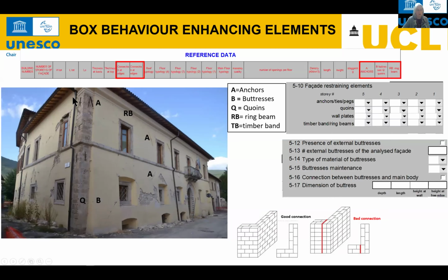So although this building looks very traditional and historic, indeed, this can be quite easily recognized as a later intervention, possibly in the mid to late 20th century, where a concrete ring beam had been introduced at the top here. You might argue that yes, this building is still damaged. That's true. We can see that the masonry fabric of the building is quite irregular and looks quite rubbly.